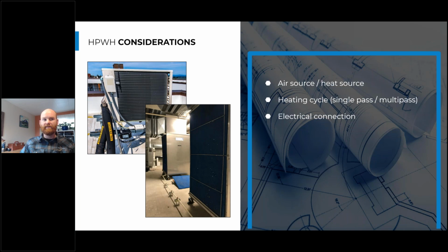Heat pump water heaters, along with electric resistance water heaters, require a bigger electrical connection, because we're using that to get energy into this water. And so it's important to coordinate that electrical connection and understand what equipment you're using and what voltage and phase it's operating at.